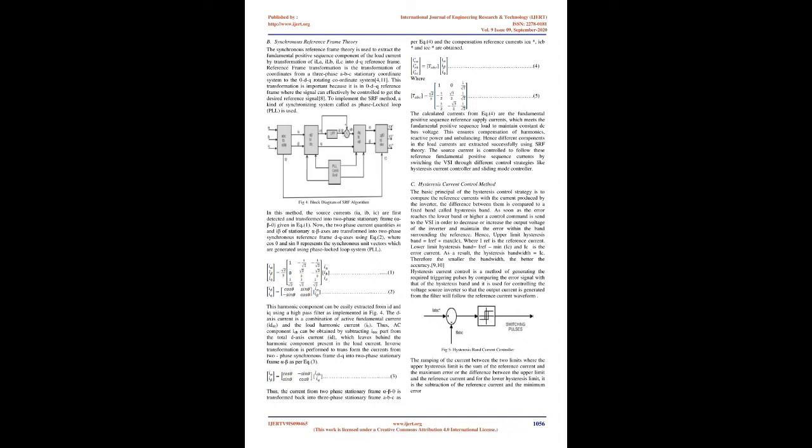Structure of shunt active filter. It consists generally of two basic blocks, the PWM converter, which is responsible for power processing and synthesizing the compensating current that should be drawn from the system, and the active filter controller, which is responsible for signal processing and determining in real time the instantaneous compensating current references, which are passed continuously to the PWM converter.